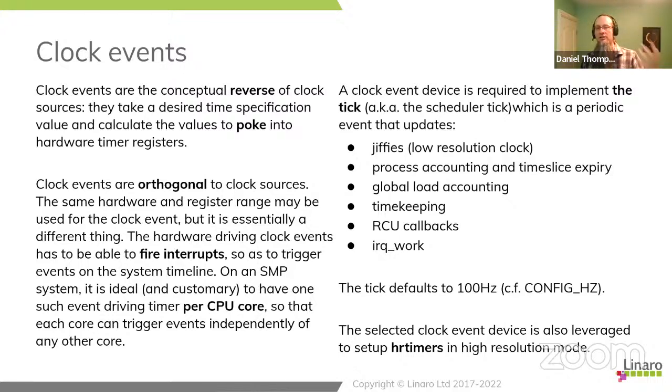Again, the ARM architecture timer is instantiated per core, not per cluster, so that we can program the clock events on a per CPU core basis. That's because the queues and wake-ups associated with a particular core will be different to the other cores in the system, because threads running on it will be waking up at different times. So we don't have to merge them all into one queue.